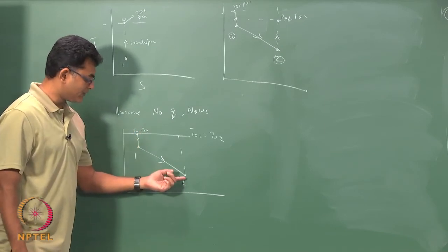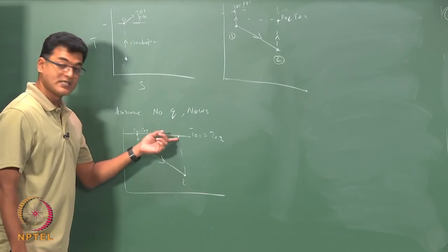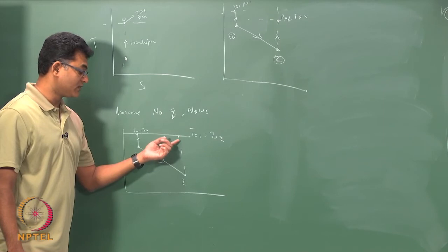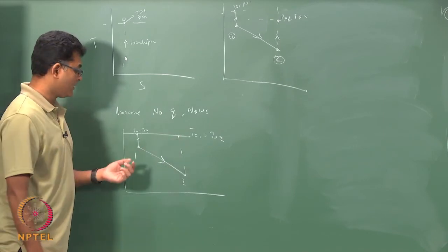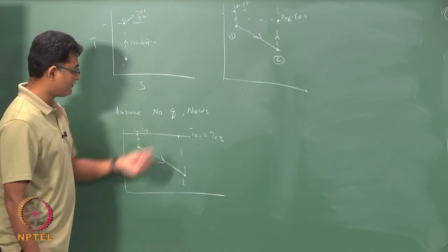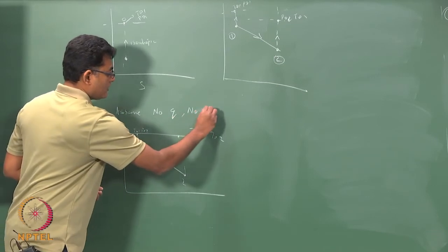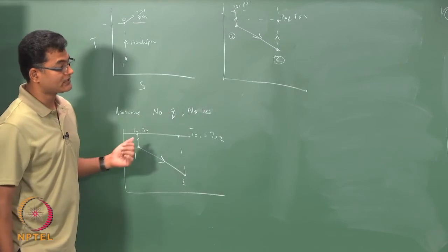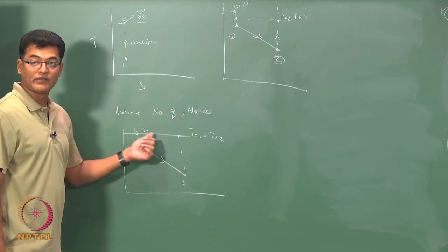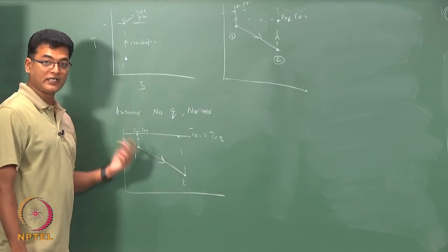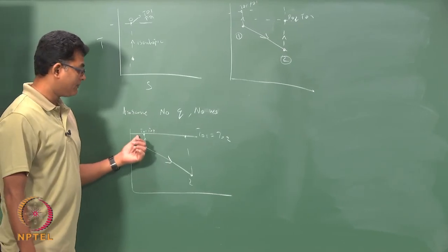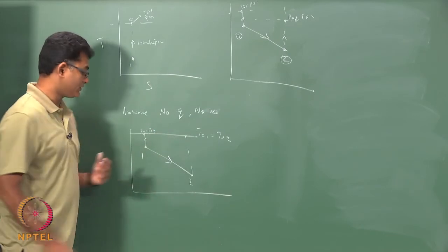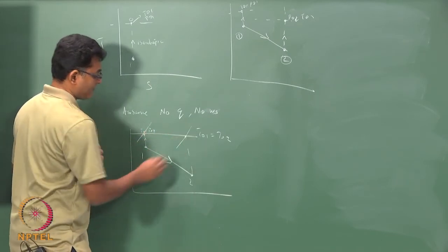Likewise, state 2 has a stagnation state with T02 and P02. Since there is no heat and no shaft work, your enthalpy is the same from the equations which we have seen. H01 equals H02, where Q and Ws are 0, and because of that the temperatures T01 and T02 are the same, but the pressures are different.